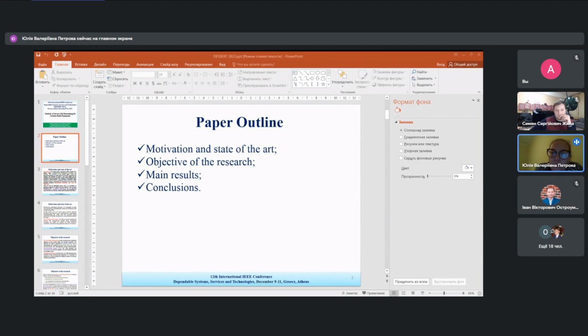The duration of the operation stage depends on the service life or remaining useful life of the equipment and is connected with the technical condition, deterioration, occurrence, and wear-out beginning. After the end of the established service life, it's necessary to perform an evaluation of the aviation radio equipment technical condition, which includes procedures for integrity analysis of all structural elements and reliability analysis. During the estimation process, it's necessary to take into account the non-stationarity behavior of failures and malfunction flow.